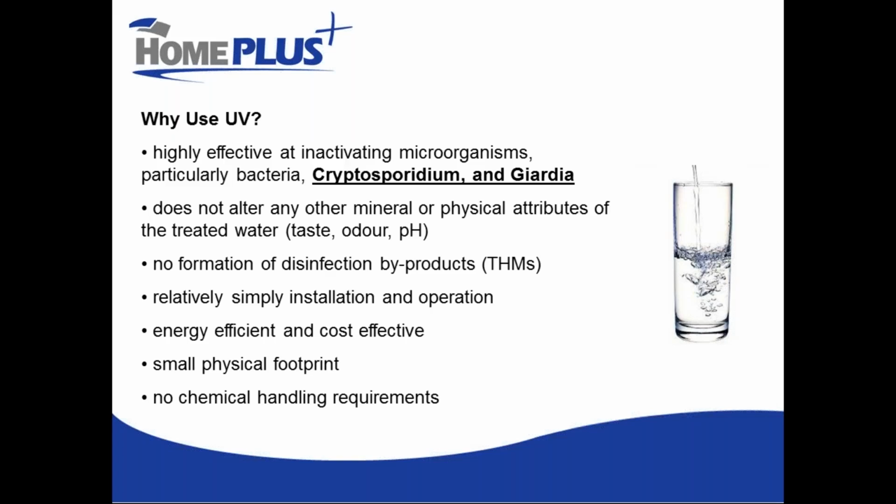One of the beneficial things of UV is that it does not alter any other physical parameters of the water other than potentially water temperature very slightly. It doesn't change any of the other attributes like taste or mineral content. It does not form disinfection byproducts.